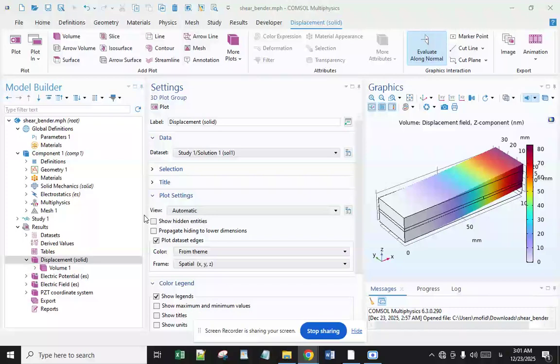Their models are based on a priori assumptions of through-thickness constant applied electric field and uniform poling, and in-plane constant stress or strain behavior. Using interdigitated electrodes (IDE), transverse actuation through the e33 or d33 piezoelectric constant can also be introduced.